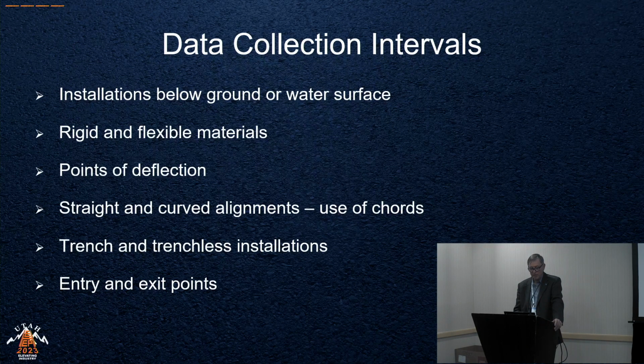The standard does include examples of how to do trenchless installation. Typically, you're required to survey your entry and exit points on a trenchless installation. And there will be a drill in most cases that has a sonde on the tip of that drill that emits an electromagnetic signal, which can be recorded at the surface.